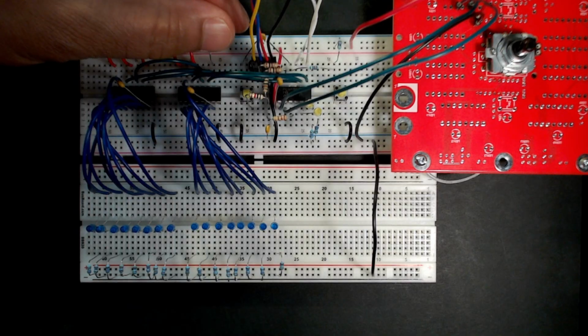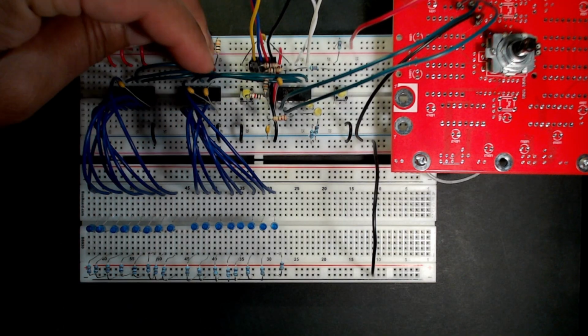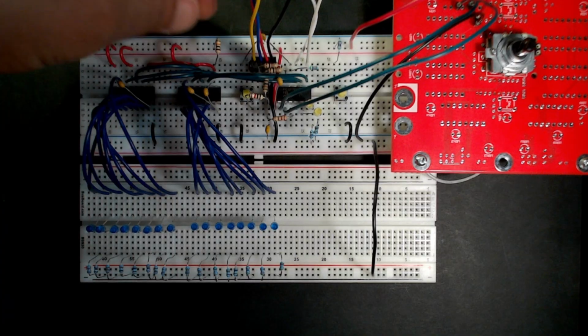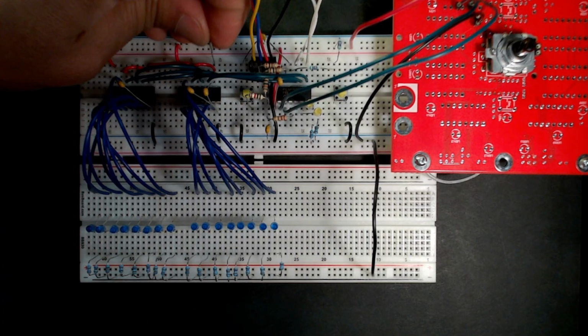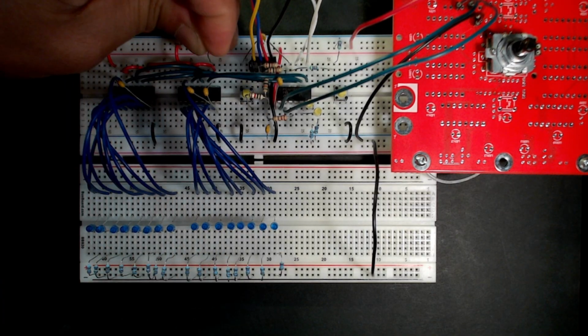To refine this a little bit more, our minimum time constant actually should be multiplied by 5, because 5 times a time constant is generally accepted as the final level. So in other words, we have a minimum of 50 kiloohms and a maximum of 640 kiloohms. Well, I happen to have a lot of 100 kiloohm resistors. Let's go with that. So all we're going to do is make sure that all the reset pins are tied together and then connected through this resistor to power and that capacitor to ground.